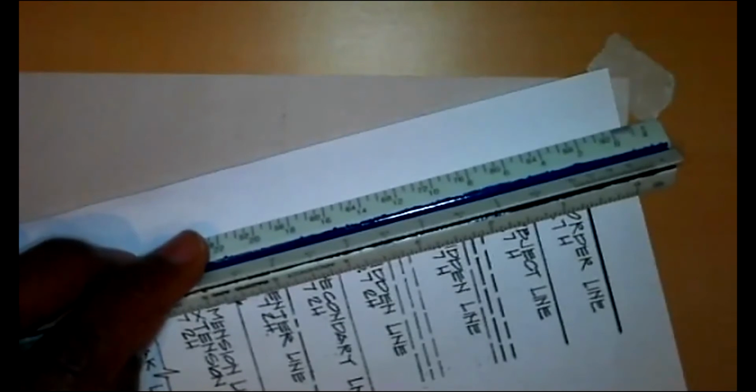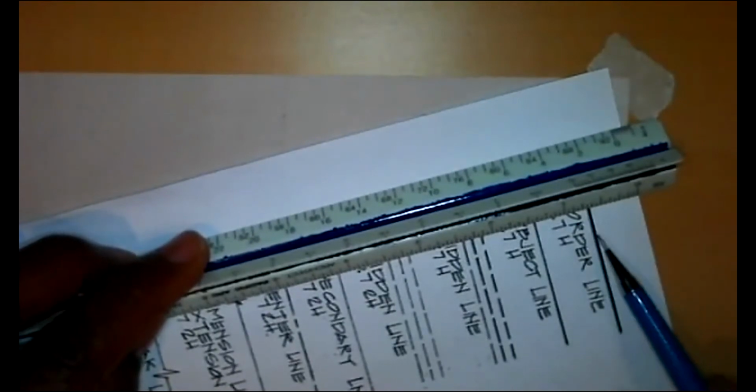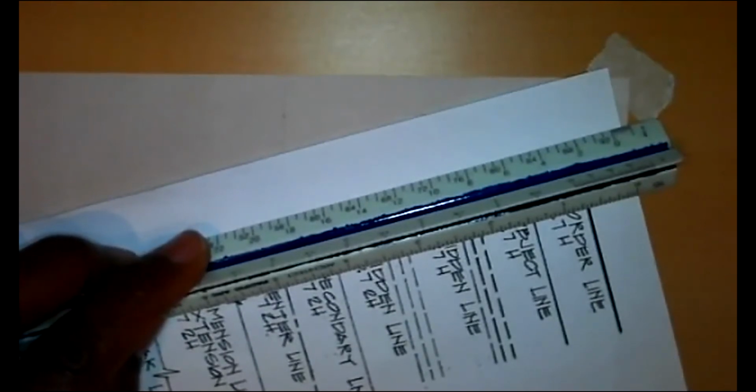Good. Right. So now, what I'm going to do, I want to locate this first borderline here, but I'm not going to draw it as a stick line. I'm going to draw it as a continuous construction line. Okay. So it measures a 1/2 inch from the edge of the paper. All right. So that's what I'm going to do. Okay. I'll come over here. And in fact, the line is already there. It's already there, 1/2 inch away. Here's the edge of the paper.